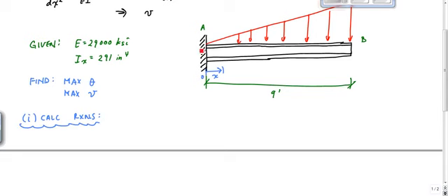So in this schematic here, really we have AY for the fixed end, a concentrated moment MA here, and AX here. Okay, and really you can draw those in any direction as long as you understand that the negative sign that you get from a global equilibrium equation means that it's going in the opposite sense.